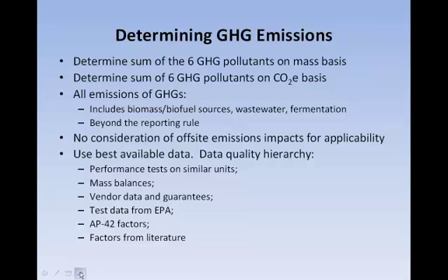Let's now turn to the task of determining greenhouse gas emissions for purposes of determining PSD applicability. Greenhouse gases must be determined in 2 ways. One must determine the sum of the 6 greenhouse gas pollutants on a mass basis, and then they must also determine the sum of the 6 greenhouse gas pollutants on a CO2e basis. All emissions of greenhouse gases must be included.